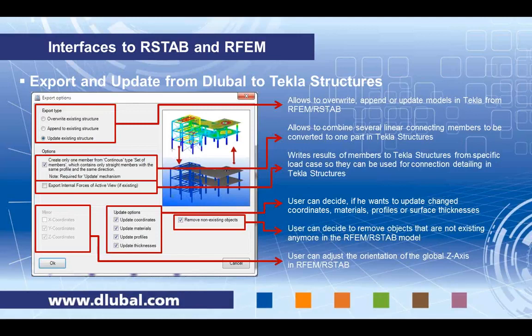So the typical workflow is that you retrieve a more or less prepared analytical model from Tekla. You do your structural design inside Dlubal, RFEM for example, and then you export the changes and you update the existing Tekla structure model. When we do this, we have different update options that I will also explain in another slide.